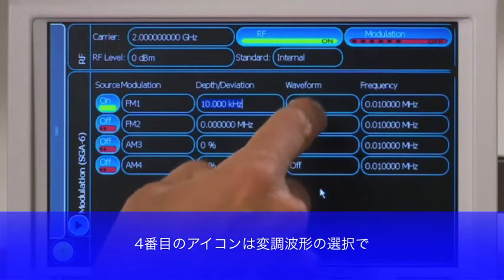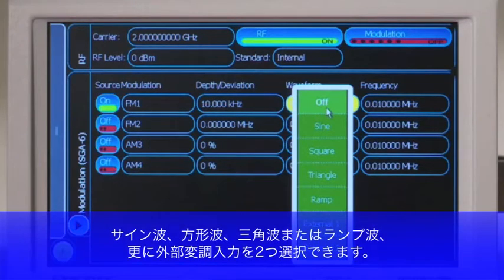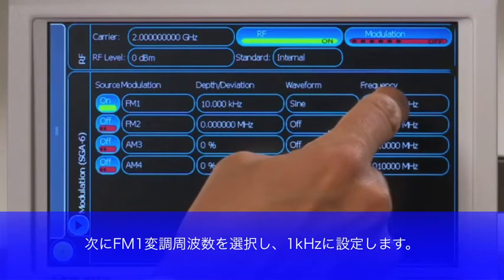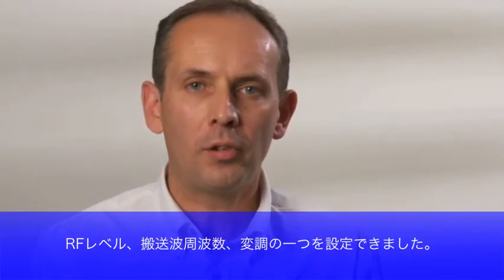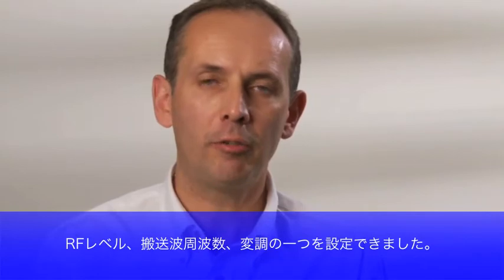The fourth column chooses the shape of the waveform, sine, square, triangle or ramp, or maybe even an external input, which I will choose sine, and I will now select the FM1 modulating frequency, which will be 1 kHz. So in 8 simple steps, I have selected and enabled the RF level, the carrier frequency, and 1 modulation path.